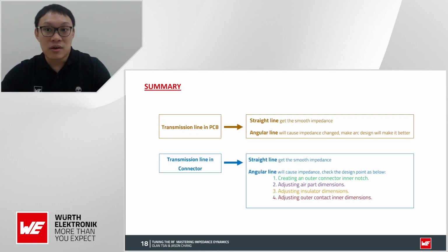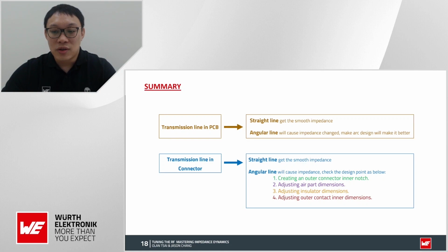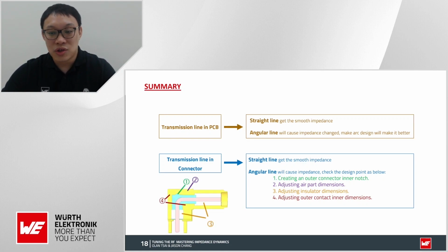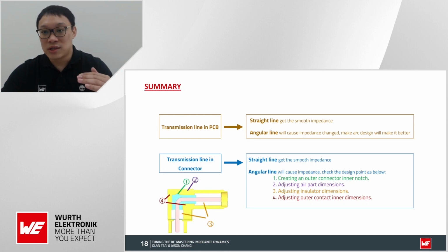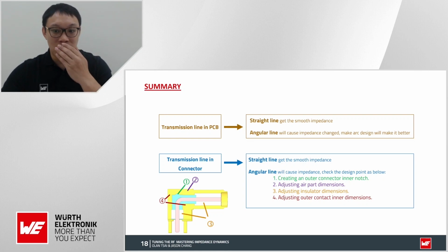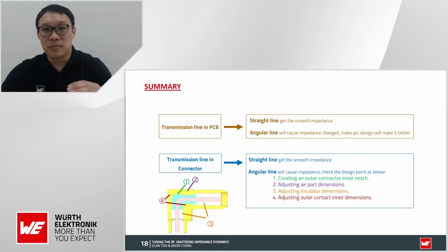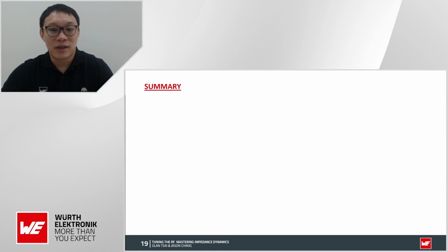And for the designer working on the connector design, try to create an inner notch and also try to adjust the ratio between the air and the inside insulation dimensions, or try to work on the outer contact inner dimensions to get a good, well-matched right angle connector.